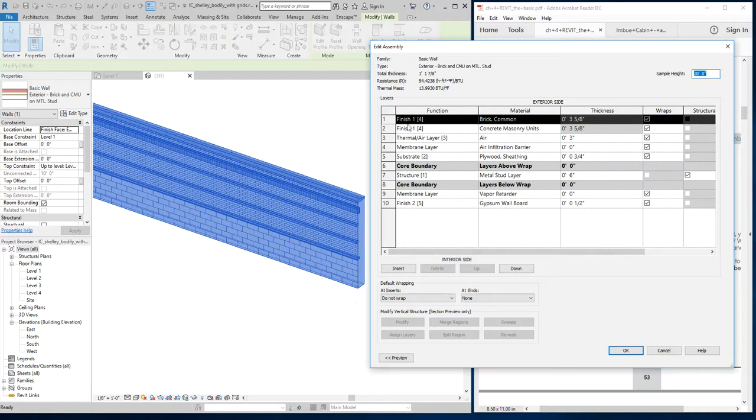And I can tell a lot of things about it, like I said, right? We can look at this and say, well, how much brick is in this project? If all these walls go from level 1 to level 2 and it's 50 foot long, we can tell the area of that. So you can schedule these things and you can figure out cost estimates pretty accurately, right? You do like wainscoting, like halfway up and all that kind of. Yep. When we get a little bit more advanced, you can split the wall up and assign different materials. We're not going to get that fancy just yet.